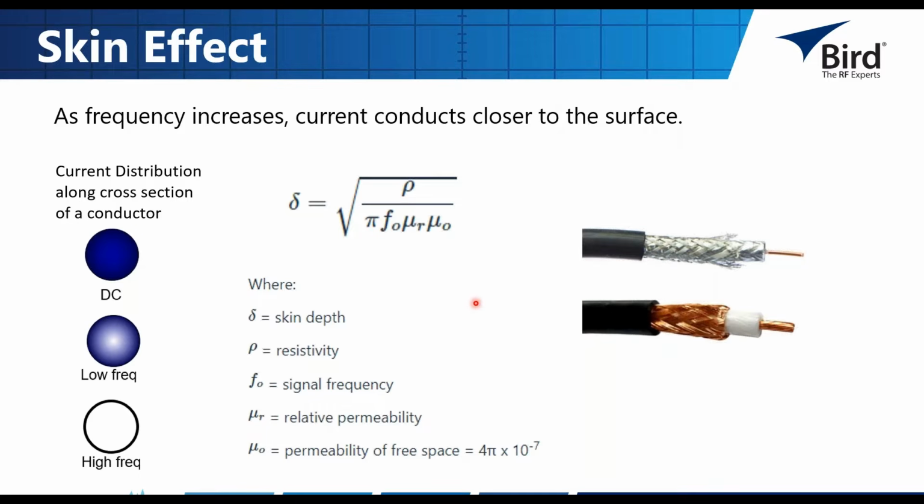Now, some things you'll see is, for example, if you had a solid conductor going down your line, you're thinking, okay, current's conducting on the outside portion of the conductor. There's also the consideration of braided cable, or where there's multiple stranded cable. In the case of something like that, as the electrons are traveling down the line, they're actually going to be traveling on the surface of these individual threads. And so you'll see people take advantage of that skin effect in applications like that. A lot of times the consideration here is just the idea of more flexibility out of your cable.